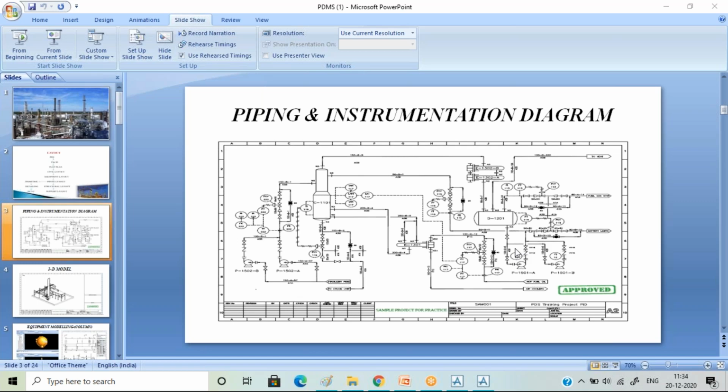So most of the time what happens is there's a one working plus one standby arrangement for the pump. Because why? Now this is a very important question. Because if one of the pumps collapses or stops working, your plant cannot stop working. No matter whether it's a process plant, a gas plant, or whatever kind of plant it is, it has to be taken care that your pump does not go into collapse. So that is why we have this arrangement. You must have also seen that in a few of the plants there is one working plus two standby pumps, and out of those two pumps, one pump is a diesel pump. So these are a few of the arrangements that we have.